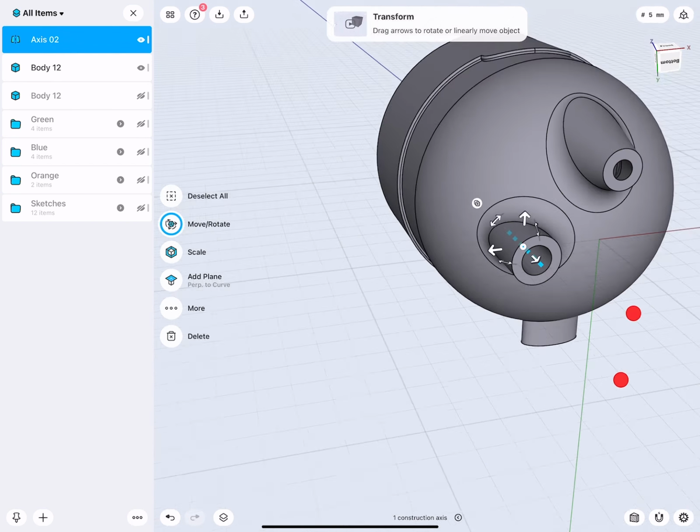And also here, I can draw a line and make this tangent, make this, for example, horizontal. I will lock this just for the sake of demonstration. Now I can move this left and right, but I can't move this up or down. And the same here, left, right doesn't work, only up and down. And then this way, very easily, I can create a nice flow of a curve where actually from this line, we do an extrusion that flows tangent into here and then terminates tangent into a line.